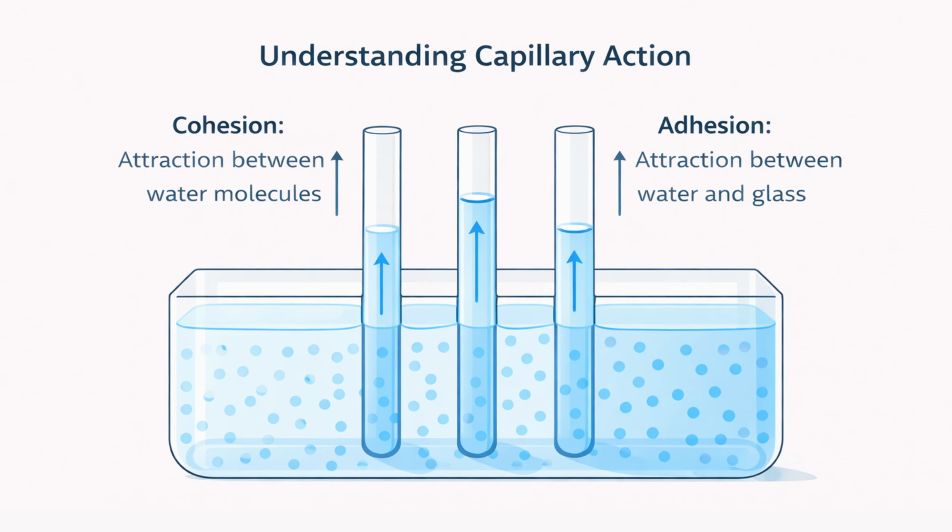The method assumes steady-state conditions, meaning it does not account for changes over time, such as varying weather or material properties. While the Glaser method focuses on vapor diffusion, it does not explicitly consider other moisture transport mechanisms like capillary action or liquid water movement. This makes it a simplified approach, suitable for specific scenarios but with limitations in addressing more complex moisture dynamics.